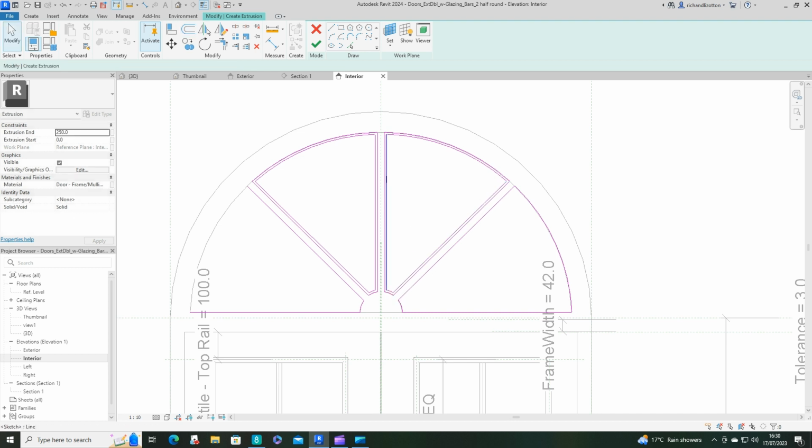Okay, now to get rid of the old lines, point at it, press the tab key, click on it, and delete, and all of them are gone in one go. So tab, click, delete.